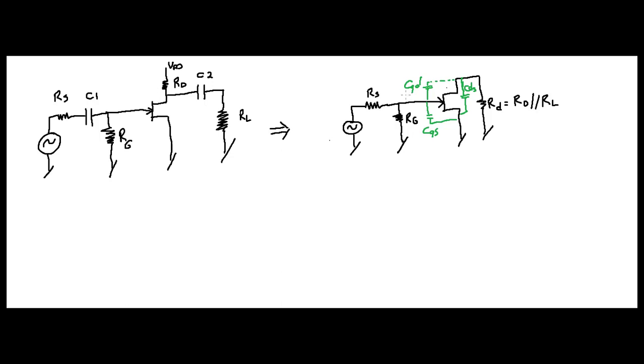Now look, here's the deal. These values of capacitors are not given directly. You have to infer them. So in the data sheet, you're not going to see these, right? At least not right now. So you're given other variables, which then you can use to calculate these values, all right? So you're given these variables right here. You're given, I'm going to write them down here, CISS. Alright? That actually stands for your input capacitance.